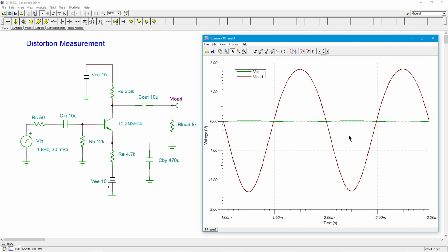If it has half-wave symmetry, that means there's no even harmonics. So if I'm starting at 1 kilohertz, the even harmonics would be 2 times, 4 times, 6 times, 8 times. In other words, 2 kilohertz, 4 kilohertz, 6 kilohertz, 8 kilohertz, and so on. So if we had half-wave symmetry, all of the distortion products we're talking about would be at the odd multiples: 3 kilohertz, 5 kilohertz, 7 kilohertz.